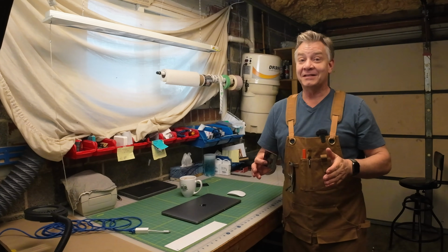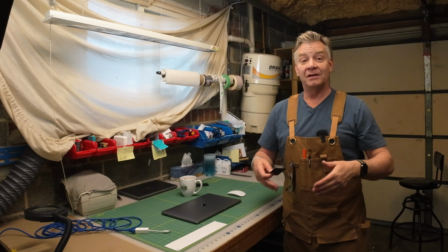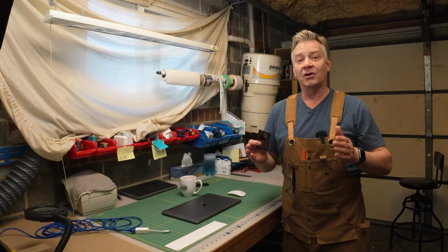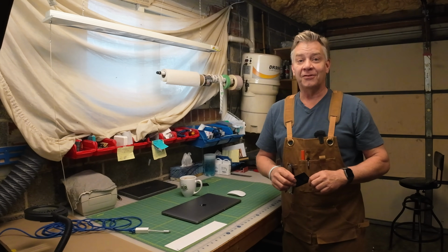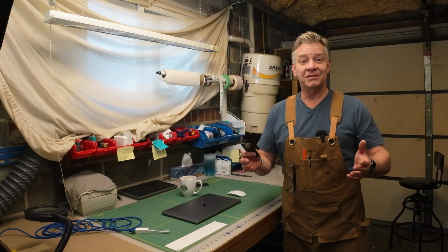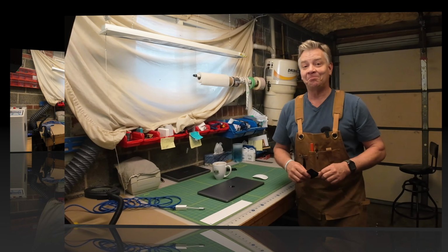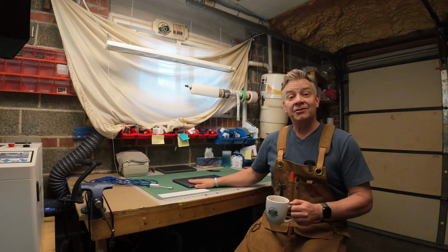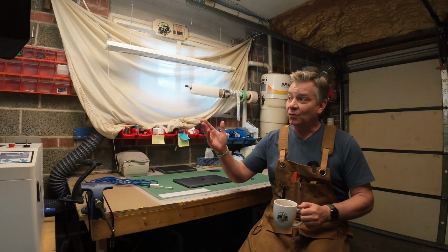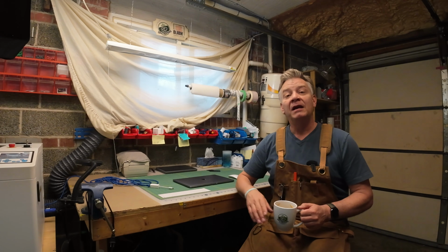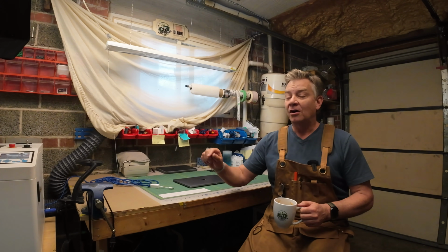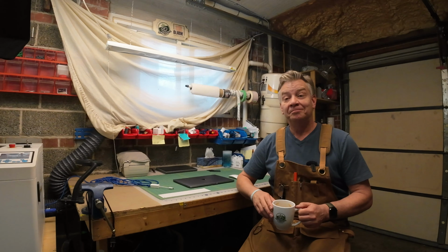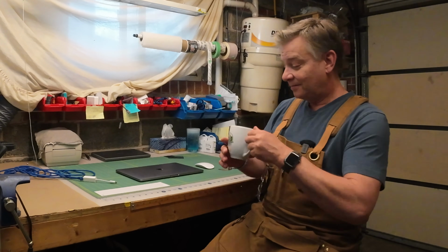And definitely, if you're making templates or something that you reproduce on the same stable template over and over again, absolute origin is your friend. I'm going to show you the difference in my own words today, and I hope it helps you out. You may have noticed, I never plugged the Bolt in, and I still haven't turned on my computer yet. I was able to just walk into the shop, turn the Bolt on, put my template in, autofocus it, and push start. It's that simple. Because I used absolute origin. Let's roll into LightBurn and I'll show you the difference.